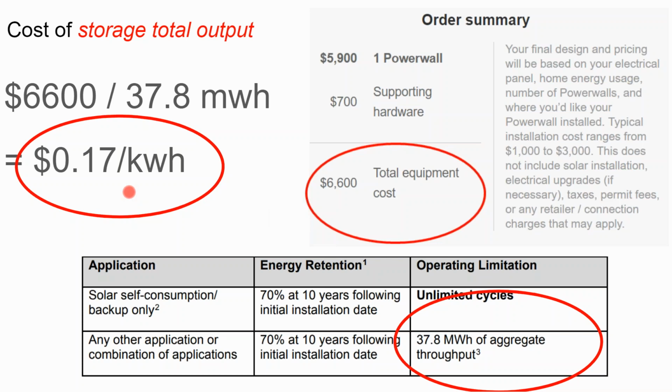What they're really useful for, what they're really designed for, is discharging over a 2-hour period. That's not off-grid living. Off-grid living, you're discharging it over a 20-hour period, and then the sun's up for 4 hours or so.